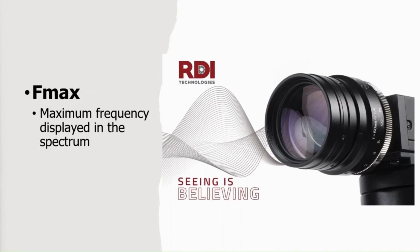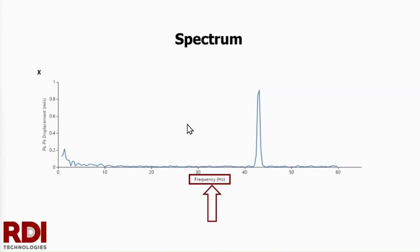And then there's one last term I'd like to define as it relates to the vibration spectrum, and that is Fmax. The Fmax is the maximum frequency displayed in the spectrum. And so when I look at this spectrum and I look across the frequency scale, the Fmax in this spectrum is 60 hertz because the data ends at 60 hertz. So if there were a vibration occurring at some frequency higher than 60 hertz, I would not see it because the measurement actually stops at 60 hertz. So in this example, my Fmax is 60 hertz.